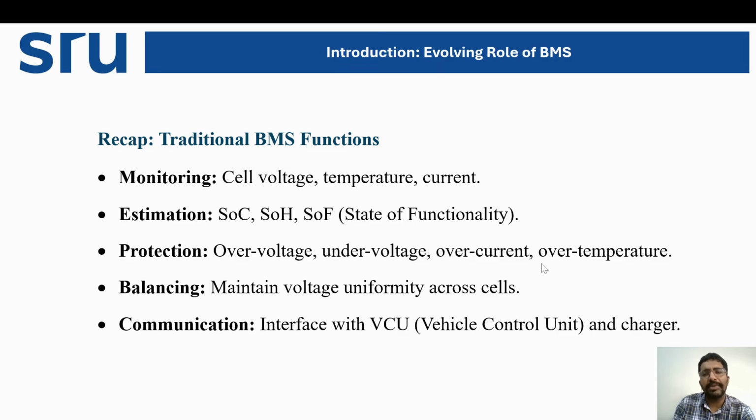It will definitely be using one of the cooling mediums like forced air, then liquid based cooling, fluid based, then immersion based, then paraffin wax, that is phase change material. So different techniques are there coming under the cooling of the batteries, that is the thermal management. Although there are other protection devices like over voltage, under voltage and over current.